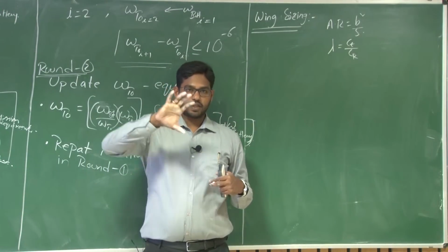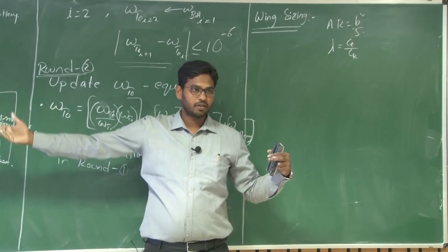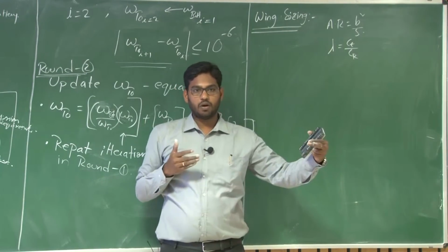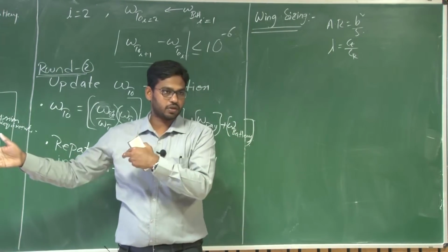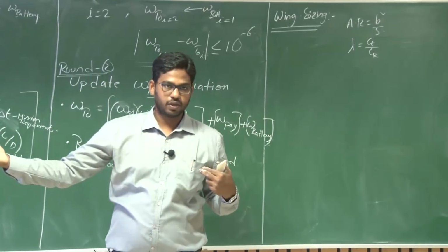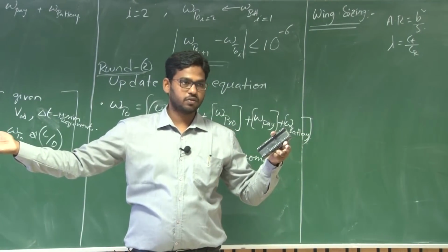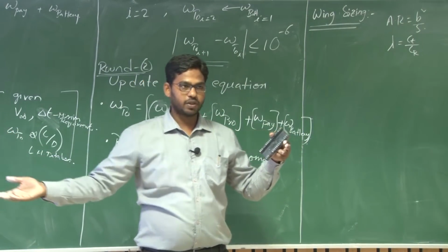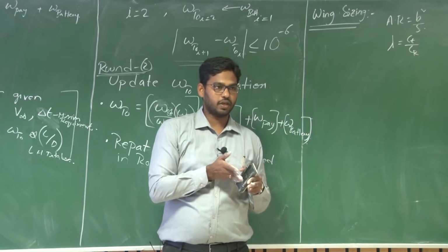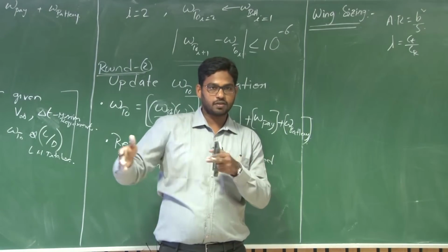And also as the taper changes, the amount of lift generated by each aerofoil changes. That means near the root you will have a bigger chord, the root chord, and as you progress towards the tip you have a lesser chord, right? So the lift generated near the root is higher compared to the lift generated at the tip, which means the bending moment about the root or the fuselage reference line is different.